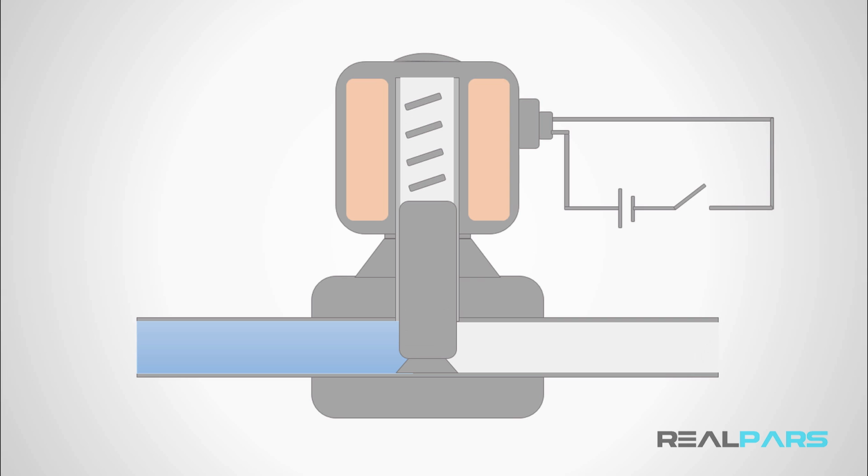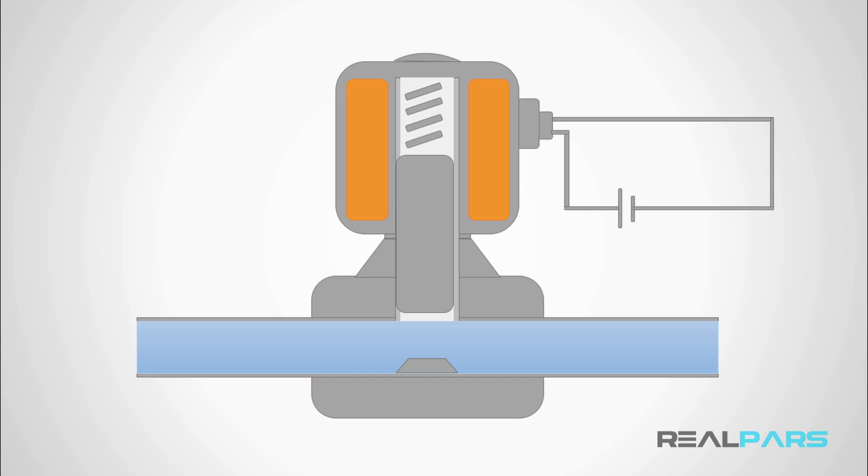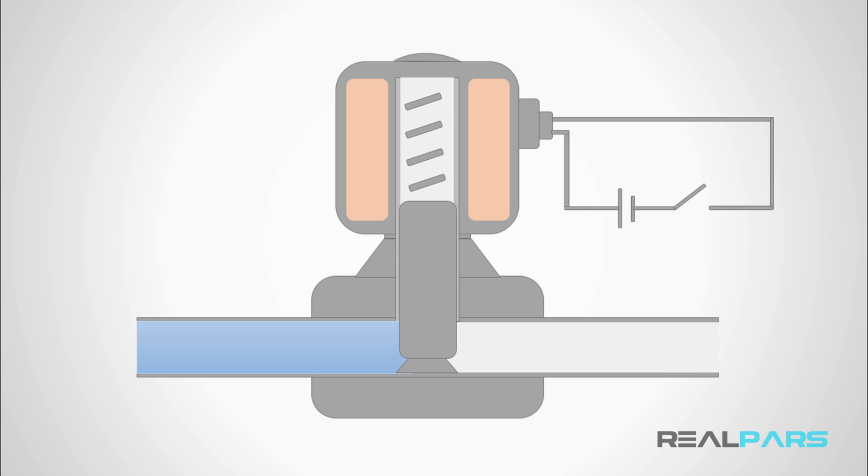Therefore, whenever the digital output module applies a 24-volt signal to the coil of this valve, it energizes the coil and the valve opens up. Otherwise, the valve is closed, and so it blocks the fluid flow.